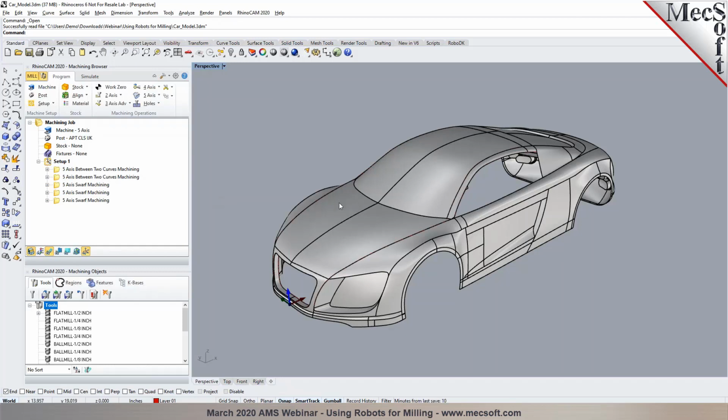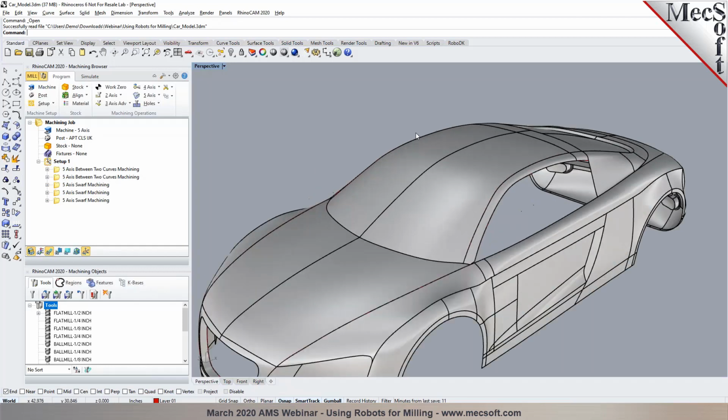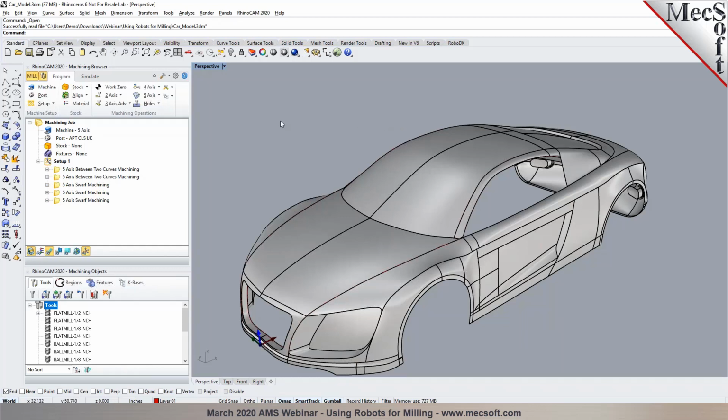And typically to program a part like this, you would still go through the process of roughing it out. For roughing, we would recommend using indexed, also known as 3+2 machining, where we rough it from different orientations or different planes. I'm going to cover that in my next example. On this particular part, we'll talk about how we can generate some 5-axis simultaneous finishing toolpaths.